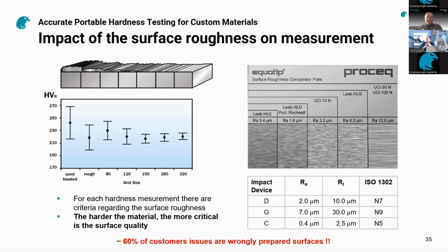what the method allows. For example, for UCI with this range, it would again depend on the test load. If we're using HV5, it would be 4%. And again, depending on the standard, there are many sub-variants of those things. Let's not forget that the benchtop would typically be 3% within that range, depending on the standard too. So with the UCI method, one is not far away.